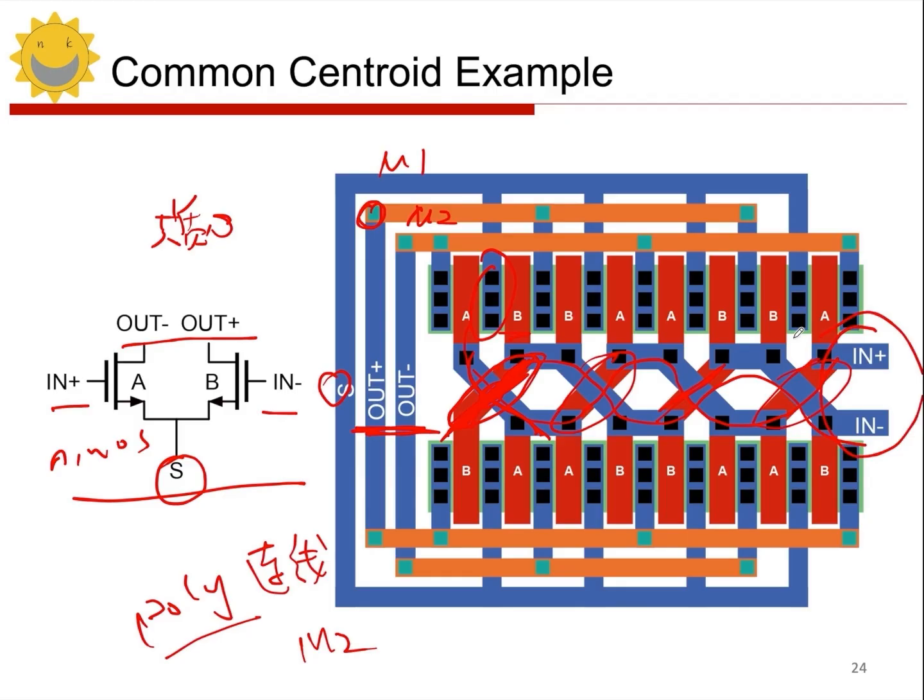So this is when we are drawing the input transistors of the operational amplifier, using this common centroid method to achieve a layout match. So it can suppress the higher order gradients in the XY directions. The changes in the parameter gradients ultimately make A and B, which are the 2 devices we processed, more consistent, right? More consistent.